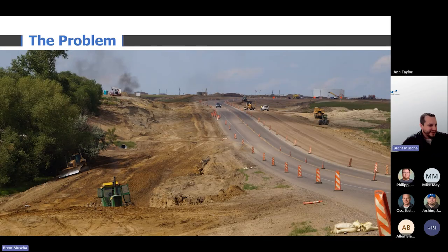This is maybe not quite as beautiful, but it's another big project where maybe you had lath that disappeared, or you marked your center line on the pavement. Now the paint marks are gone. And you want to go take a test on the left side of the road there where they're running the sheep's foot. How are you going to figure out what station you took your test at?